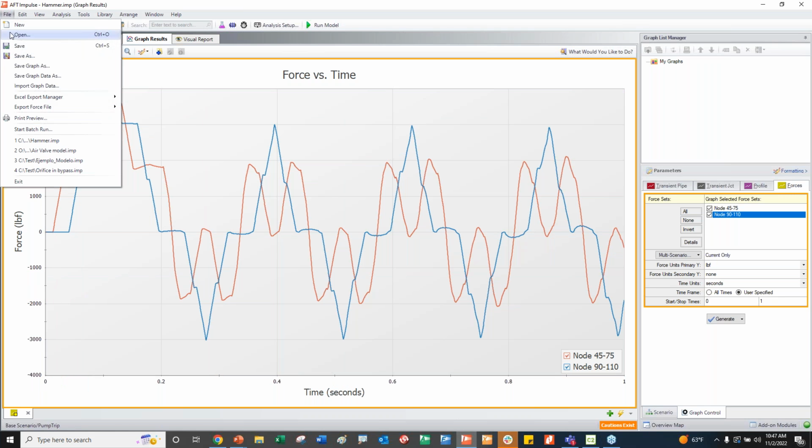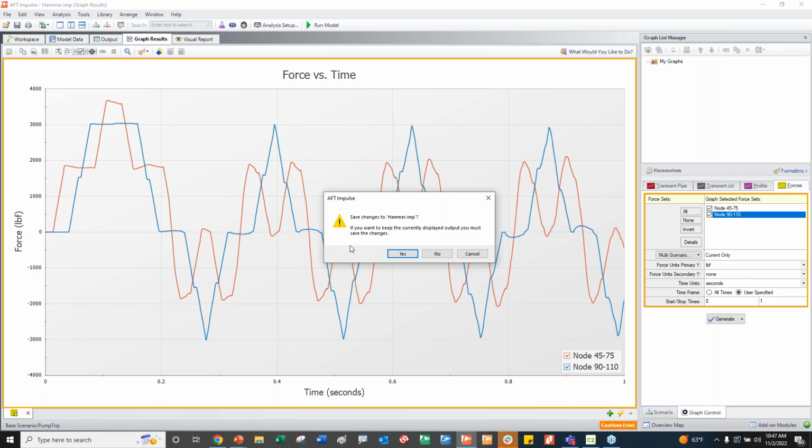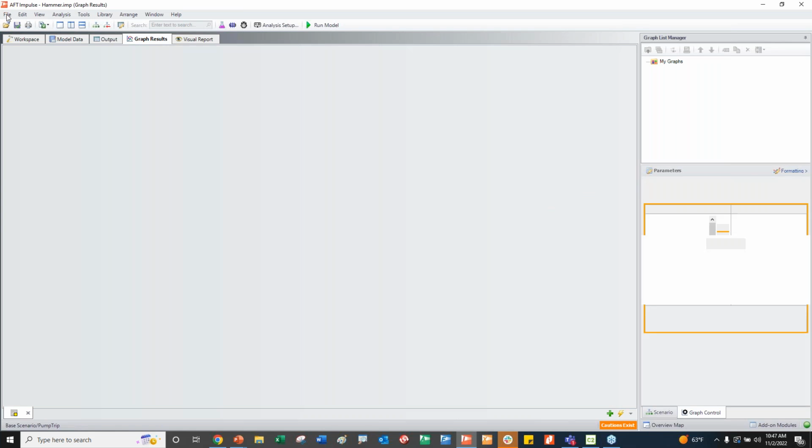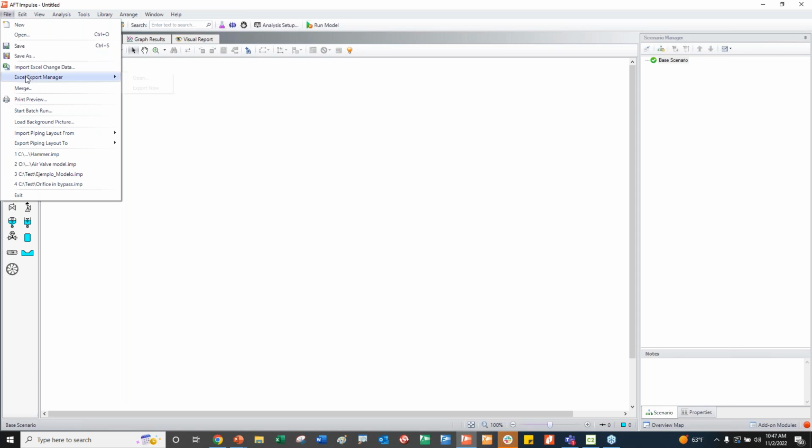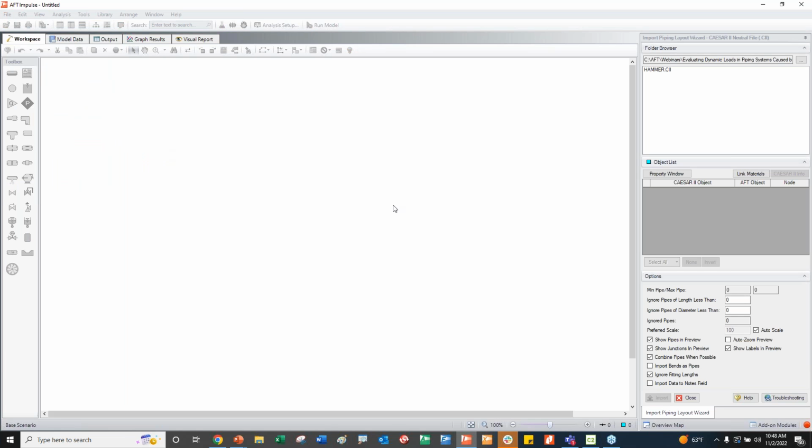So you create it from Caesar, and then in Impulse, I'm going to create a new one. You come here in Impulse and you say import pipe layout. You come from Caesar.